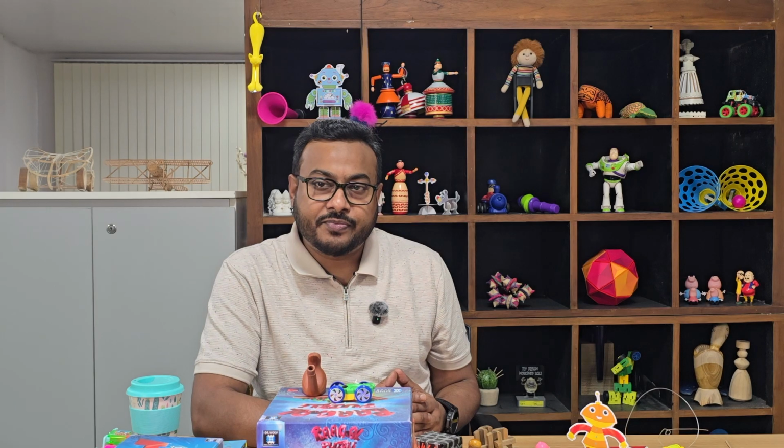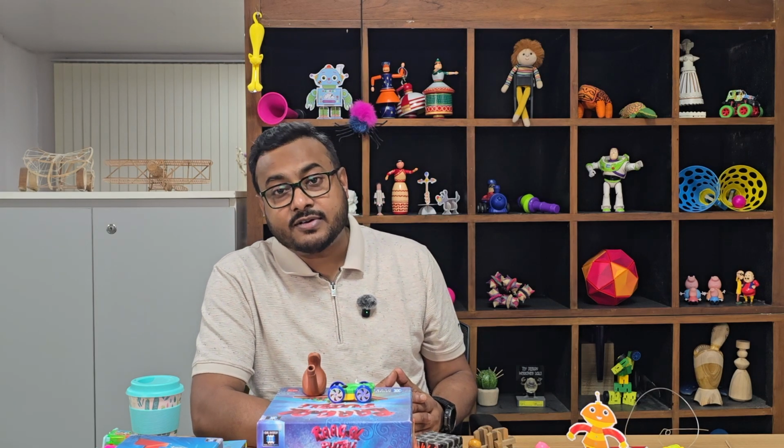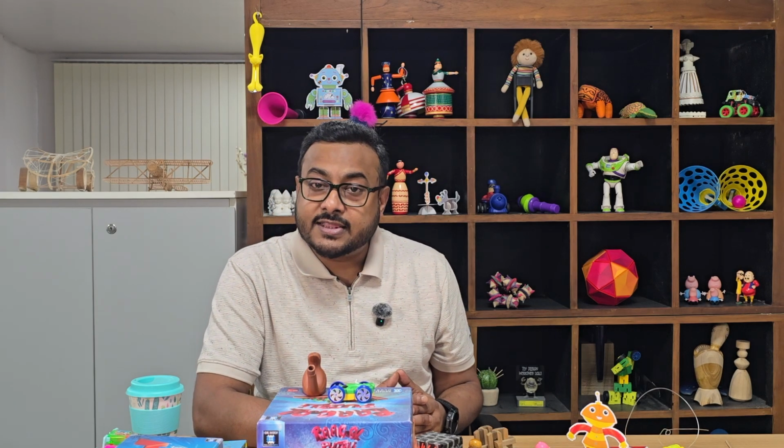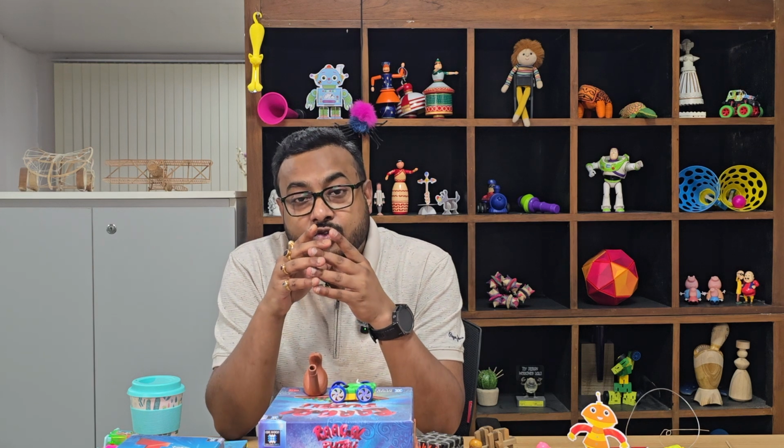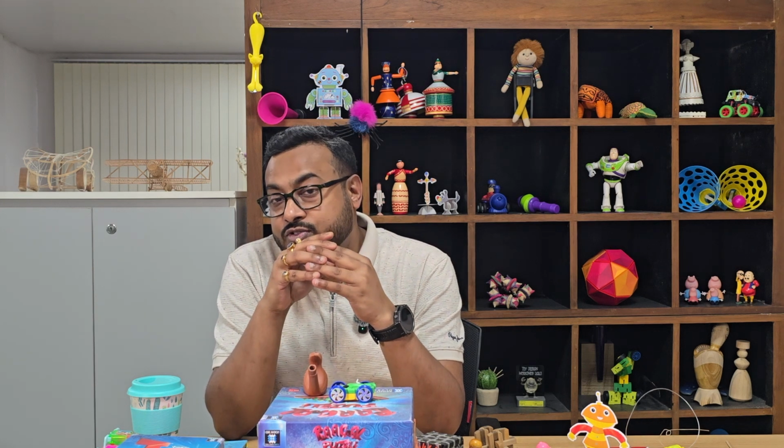Now connect that to grip strength data. For 4 to 5-year-olds, grip strength ranges from 2 kg to 8 kg. This means a child in the lower percentile may only exert 2 kg of maximum force. If your toy requires sustained pressing force near that limit, fatigue will occur within minutes.